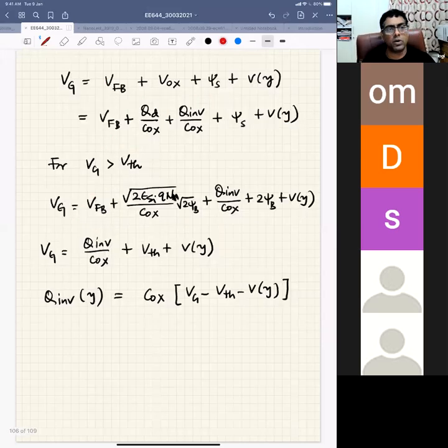Now, if you understood the band diagram, then let's go to the gate voltage, because I need charge. For current, the first thing I need is charge. So let's go back to our earlier equation. Your Vg is flat band voltage plus voltage drop in the oxide plus voltage drop in the silicon. The voltage drop in the silicon will be psi s plus Vy now.